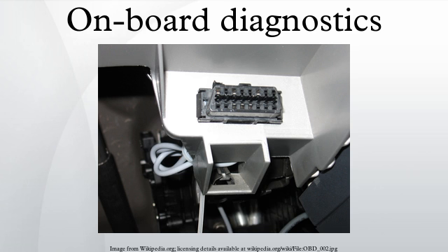PC-based scan tools and analysis platforms. A PC-based OBD analysis tool converts the OBD-II signals to serial data standard to PCs or Macs. The software then decodes the received data to a visual display. Many popular interfaces are based on the ELM or STN1110 OBD interpreter ICs, both of which read all 5 generic OBD-II protocols. Some adapters now use the J2534 API, allowing them to access OBD-II protocols for both cars and trucks.